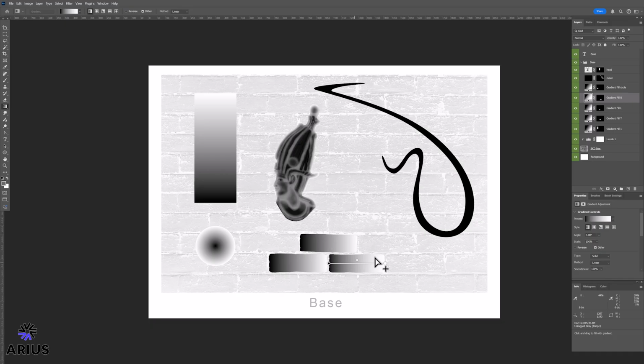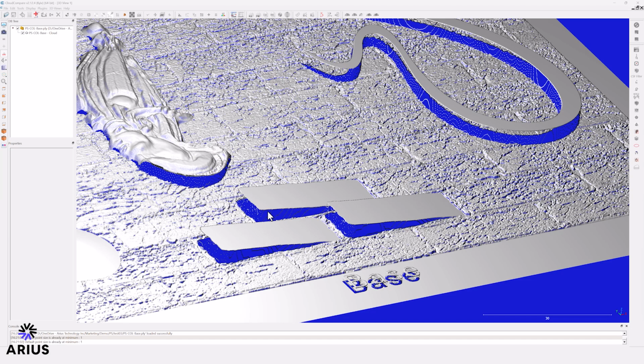To create this flat geometric surface, avoid using the method labeled linear, despite it seemingly being the logical choice. Instead, use the classic method and adjust the smoothness slider to 0. That will produce the flat surface often referred to as linear here. With these high contrast areas at the edges, we'll get walls here and here, but that will elevate like this.